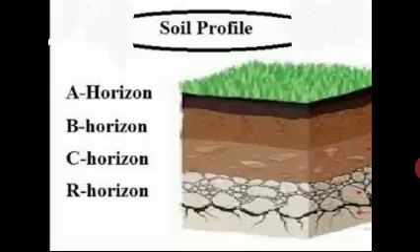The next physical property is pH of the soil. pH value or negative hydrogen ion concentration is a measure of the intensity of acidity or alkalinity of a soil. Its value ranges from 0 to 14, of which 7 is neutral in the sense of chemical reaction. Below 7, the soil is acidic; above 7 it is alkaline. Soil productivity increases as pH approaches neutrality.